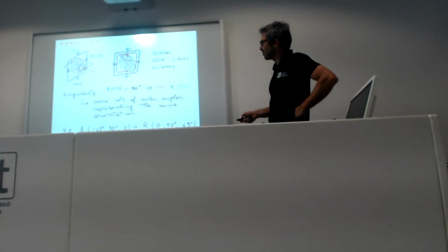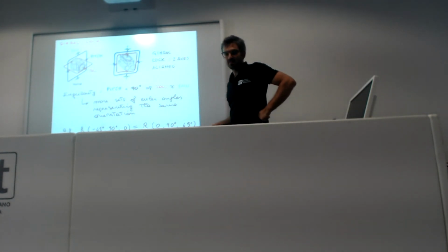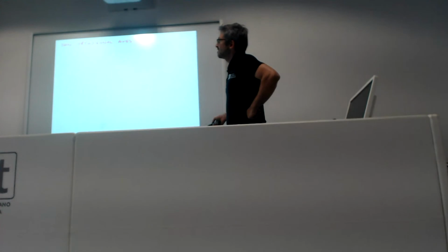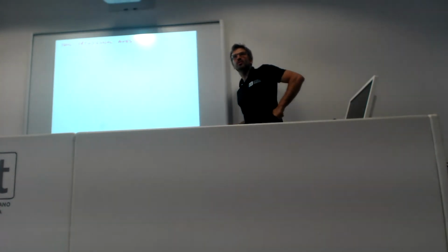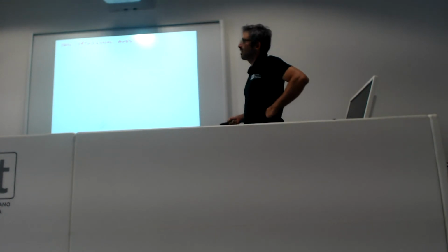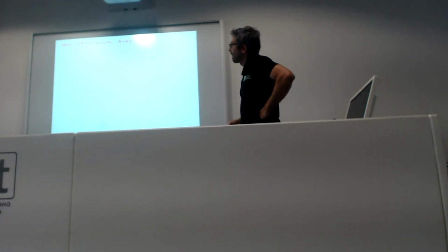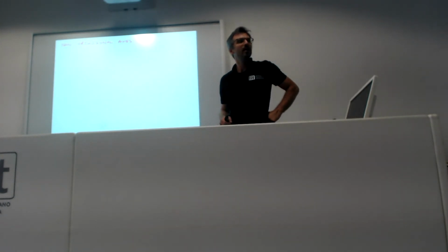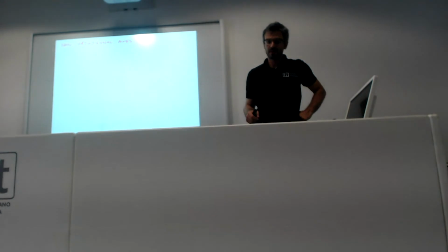This means that, for example, these two sets of angles result in basically the same rotation matrix. And this is a problem for your controller, because whenever you get there, you can get whatever number, in a sense. Now can I see that I will have, I don't know, in the matrix some rank deficiency or something like that?